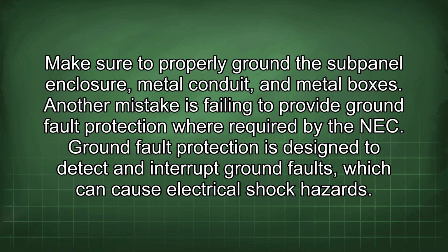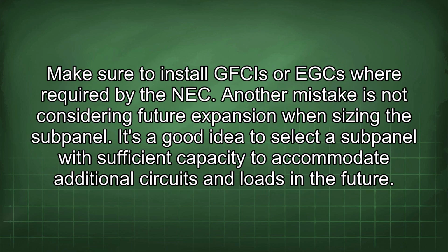Another mistake is failing to provide ground fault protection where required by the NEC. Ground fault protection is designed to detect and interrupt ground faults, which can cause electrical shock hazards. Make sure to install GFCIs or EGC where required by the NEC.